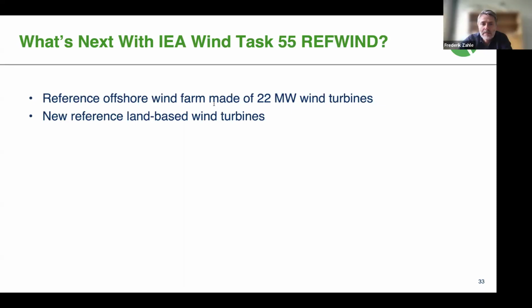There's a quick one here about the cone angle. Cone angle is 4 degrees, with a tilt angle of 6 degrees also. There is a question about the OrcaFlex model, and yes, Orcina has developed a model for the 22 megawatt. The model is publicly available on the Orcina website, and there is a link in the README on GitHub. We have not run a comparison to the Mingyang 22 megawatt that was announced last year. We don't know how the two models compare.